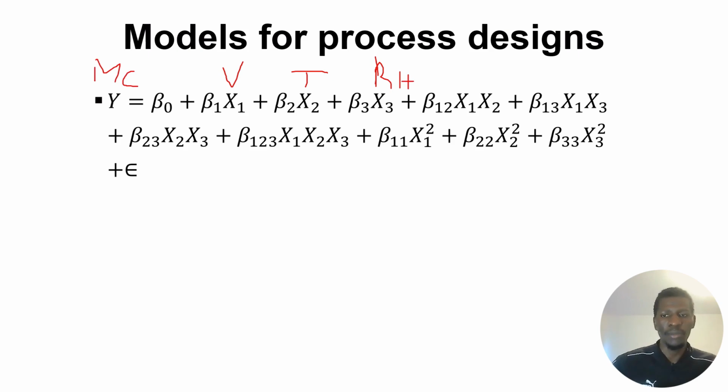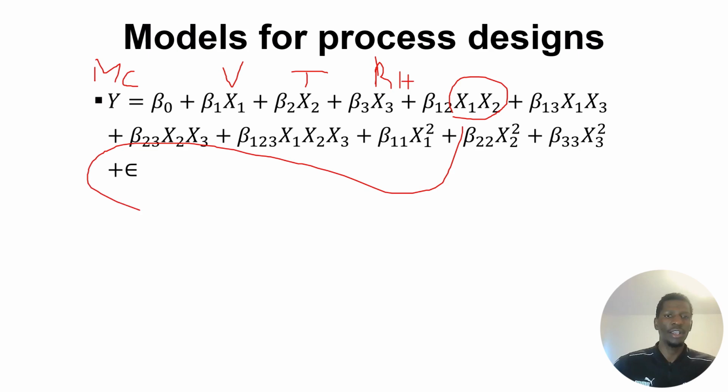So to develop a quadratic model for the three terms, we are looking at the intercept plus the three effects of the single factors as they affect the drying rate, the combination between the two factors, that is the interaction terms x1x2, x1x3, x2x3, and then x1x2x3. And then the quadratic term is the interaction between each factor and itself.